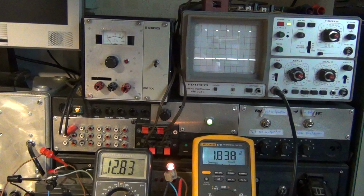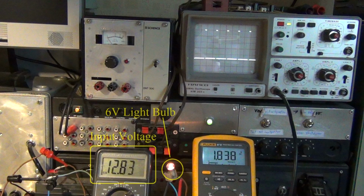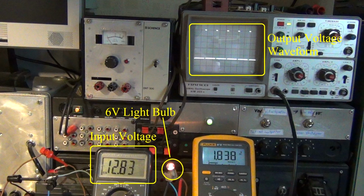Here you see the experimental setup. On the left DMM, the input voltage across the battery is displayed, and in the middle you see the 6-volt light bulb. On the oscilloscope screen you can see the actual waveform of the voltage across the bulb, and on the right multimeter the mean value of that voltage is measured.